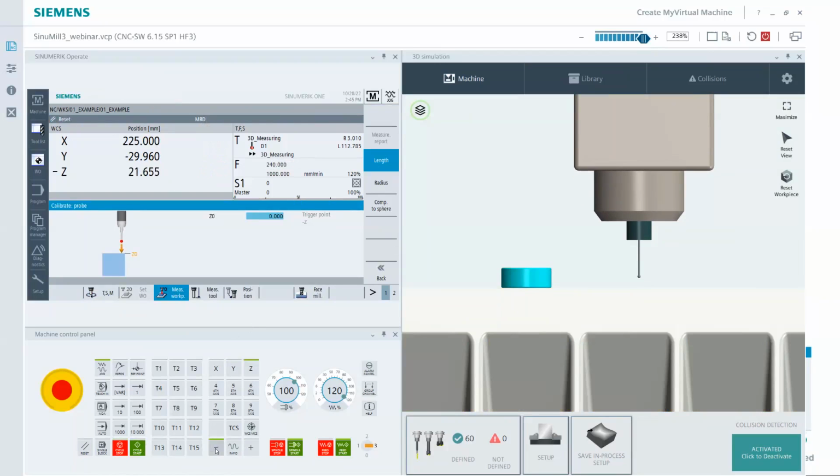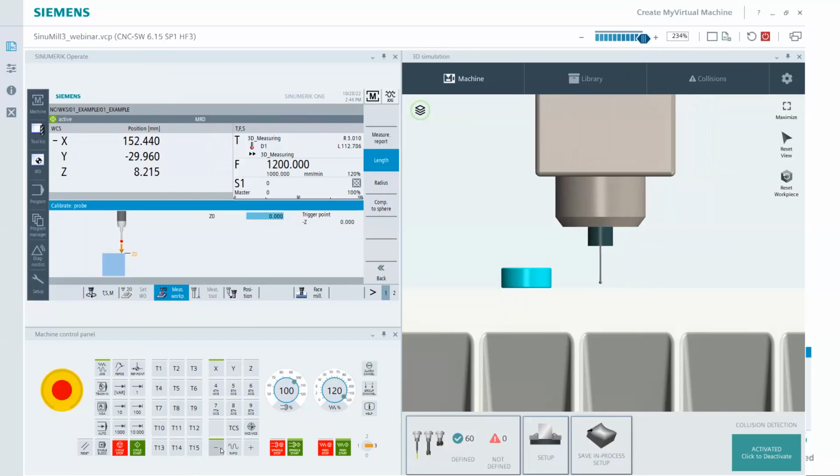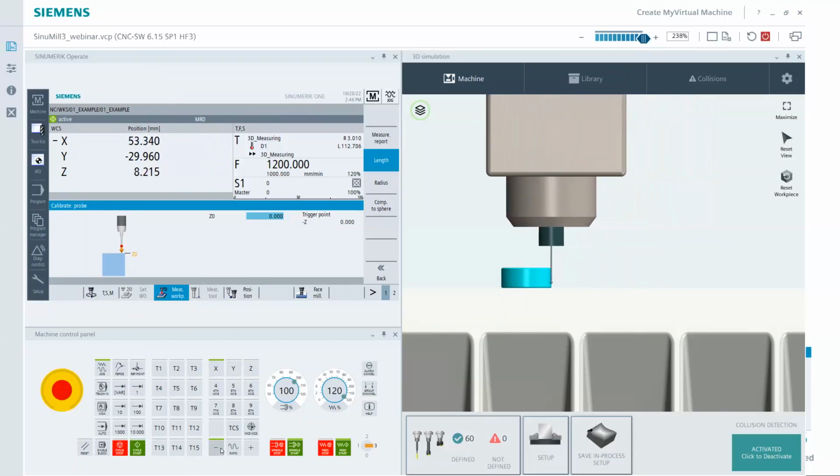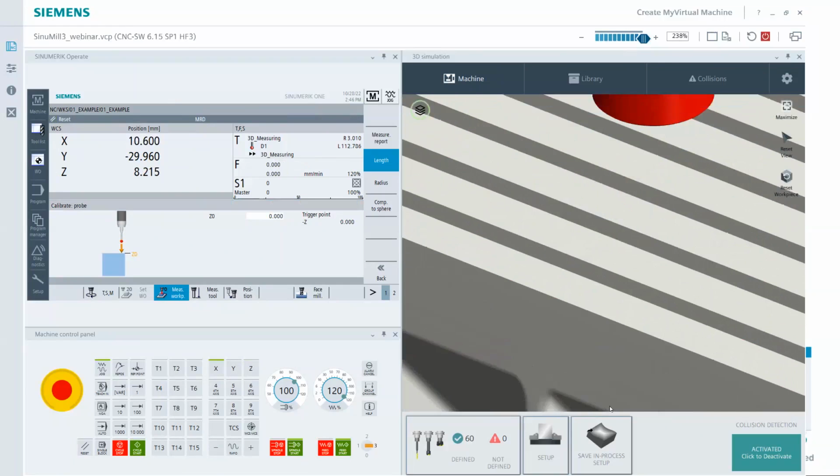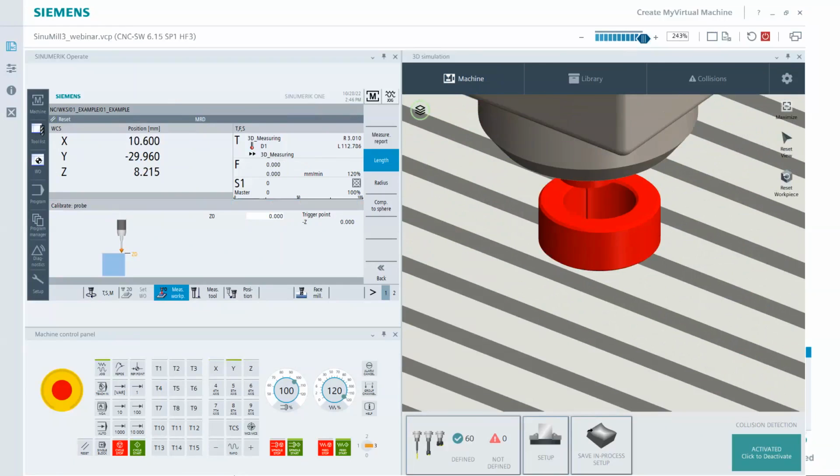The way our probing works is it's triggering off the collision. So it uses the detection point. It doesn't acknowledge it as a collision because it knows this is a probe, but that's how it knows to simulate the probe switch, is actually with the collision. So it's a real probing process for sure. Now you can be lazy and drive things right through other objects if you want. That's okay. In my case, I want to get this machine